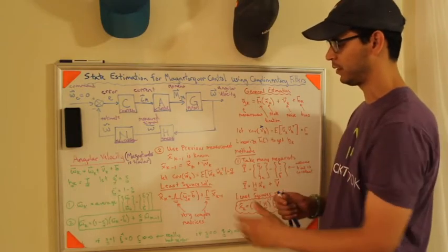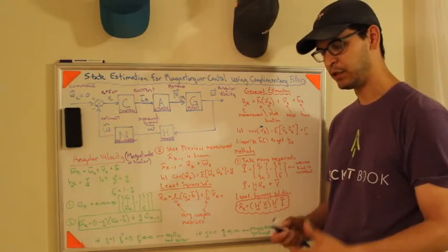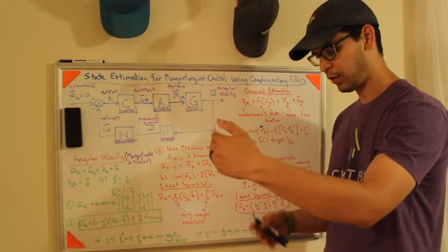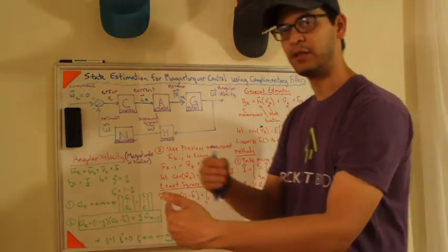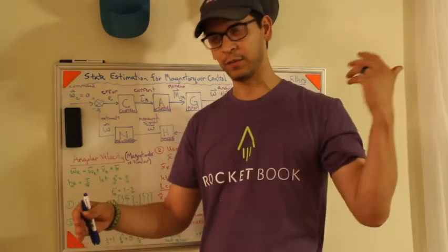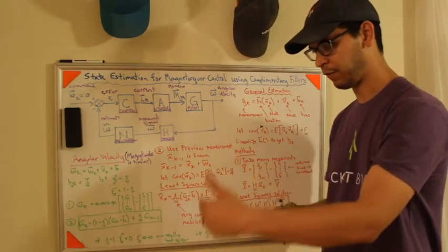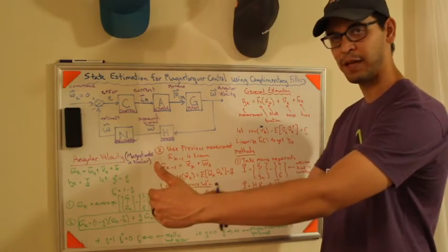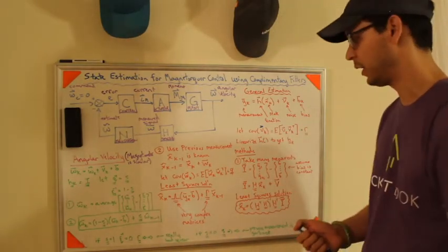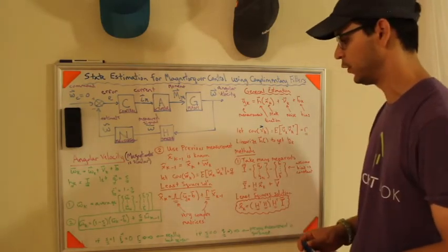The second way is to use the complementary filter. So the idea is that at the kth time instant, you're going to get an estimate. Well, what happens at the next measurement? Are you going to just throw that measurement away and redo the least squares? And then when you get to the next measurement, are you going to throw the previous ones away and just use the next one? It would be nice if, as you propagated forward, you used the previous measurement in your calculation to help you estimate the future state. And that's known as a sequential linear least squares estimator and sequential filters.